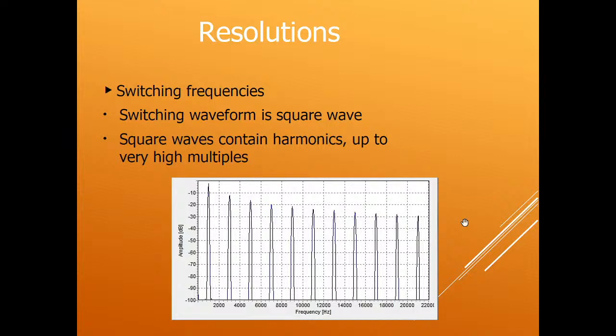And you can see that the first couple drop off quite a bit, but then it kind of levels off. So when you get up to the 21st harmonic, it's only down about 28 dB from the fundamental. And those harmonics can continue on up much higher and get into frequencies where you're concerned about in the ham bands.